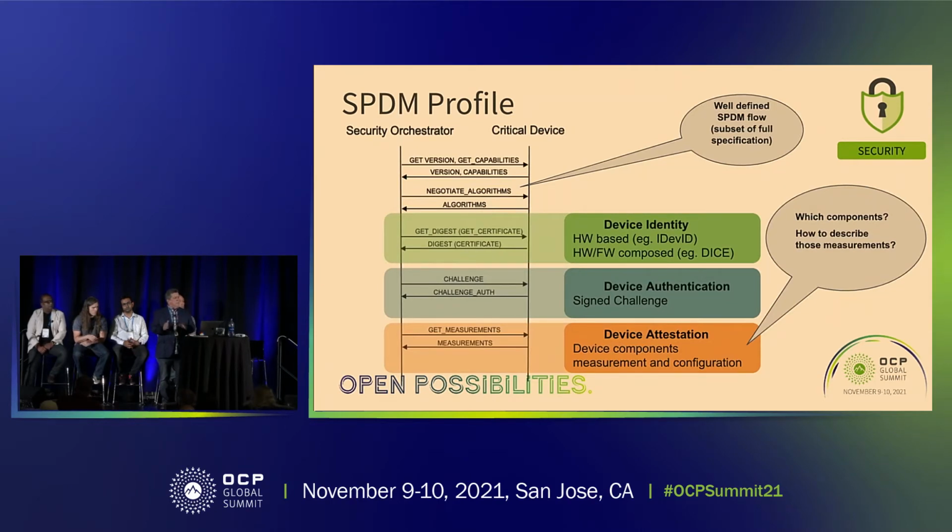Now I'll talk a little bit about SPDM. SPDM is an interesting protocol in that most of the functionality in SPDM is optional, with the exception of these two responses and two requests at the top. So you have to define a profile to say, if you have a device that is to participate in this architecture, what kind of functionality should it be supporting from SPDM? What kind of commands do we expect that it is going to respond to?